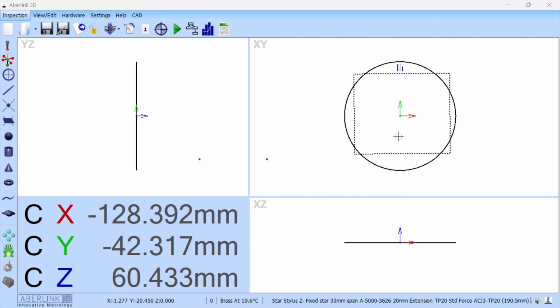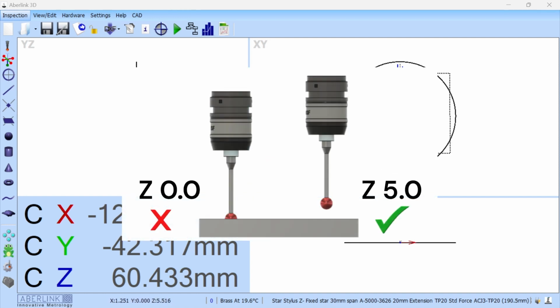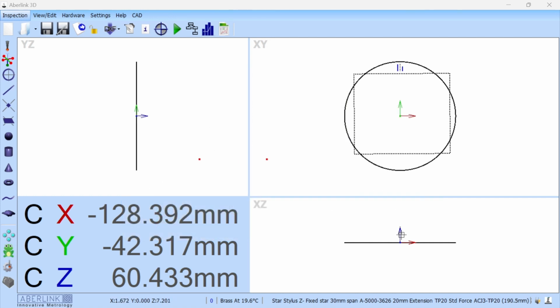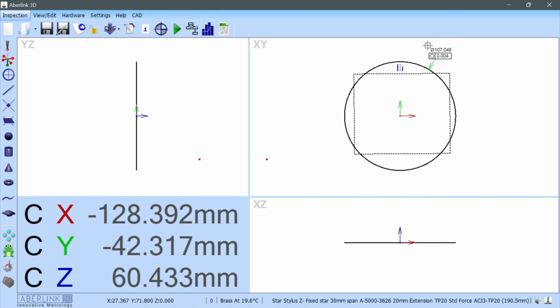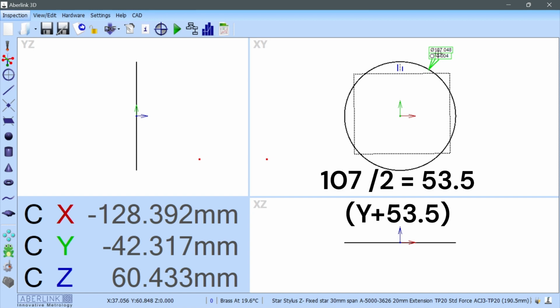That's important so that you don't get the polarity of your positions wrong, which can obviously cause a crash. In this example, we need to decide where we're going to put the pauses and the move wire. Ideally, I want it slightly above the face, so the Z value will be something around 5, but I'm going to insert a couple of move wires to traverse directly above the point and slowly come down. The X value is obviously going to be 0 because I want to sit it centrally aligned through the rotation. And then the Y position, I want it somewhere near the slot. I don't want it too close inside this diameter, so I'll probably put it on the edge of this diameter. If you're ever unsure, you can just create the dimension roughly, and that's giving us roughly a 107 diameter, which means I want my Y value to be 53.5.